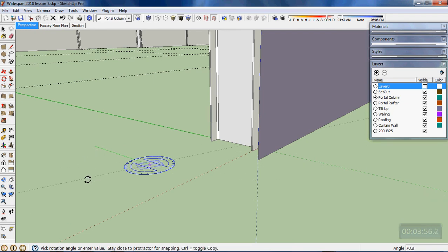Now when you are rotating things, you can actually turn it around and it will snap to the 90 degree position. I never trust it. I just rotate and give a direction and then type 90 and press enter. Depending on your mouse control, you're probably better off typing the figure rather than letting it snap.